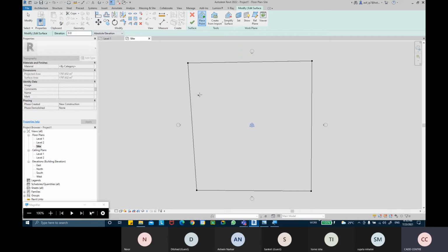Then I wanted the topo surface to gradually rise. So I'm going to say it's going to rise to around 250 mm. I'm going to place some points, and I'm going to create some topo surface. All these points that I'm creating are at the same elevation height of 250. And I'm going to say again that it's going to rise more. Maybe I'm going to give 350 this time, so another 100 mm. It's going to rise.